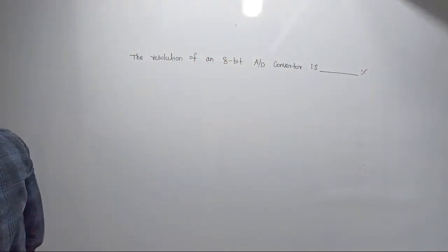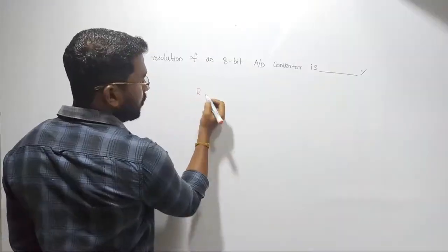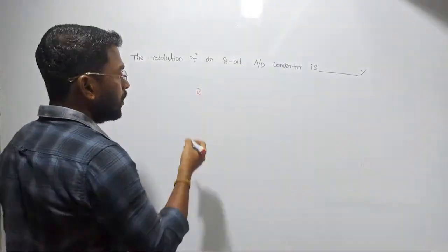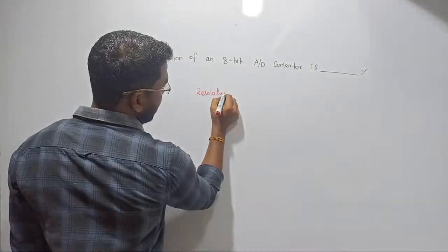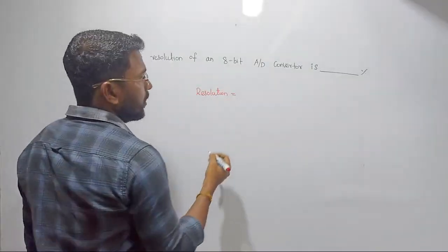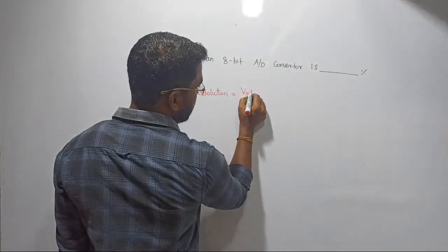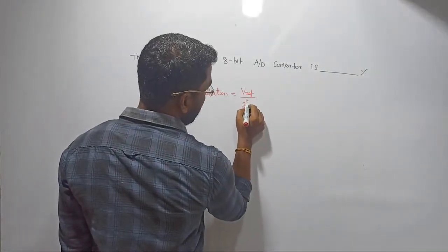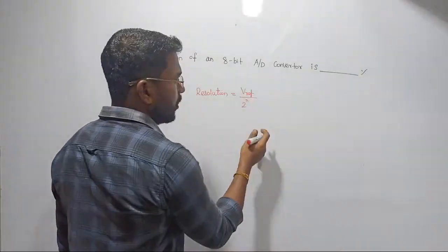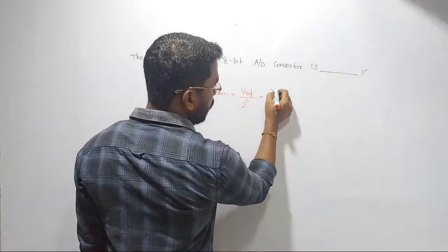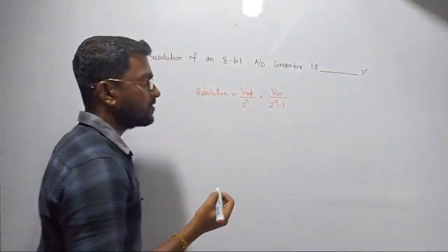Actually it's quite interesting, guys. The thing is, listen, already we have seen resolution equals step size equals 1 LSB, right? Anyway, the general formula we saw to find out the resolution, without percentage we can define like this. You can consider V reference upon 2 power n minus 1. That is with the reference, we are not considering this one, right? If you are going up with the input voltage, of course the 2 power n minus 1 will appear, right? This is the general formula.